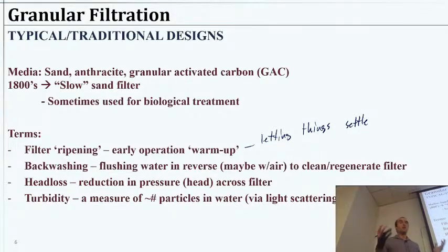Next, we have the term backwashing. Kind of already introduced it. We are putting the system in reverse. We're taking clean water and flushing it backwards through the system. And by clean water, I mean water we've already filtered. We throw it through reverse. Maybe sometimes we will add some air into this process, as we'll see, to help shake up all the particles, to shake loose all the dirt. And then we are going to collect that dirty water and send all that to waste.